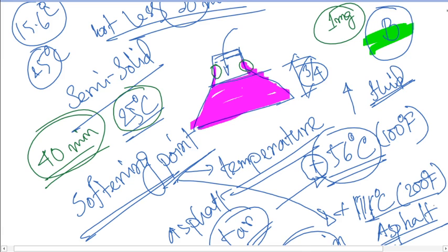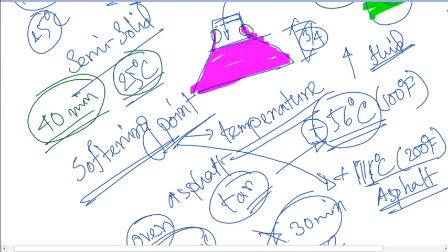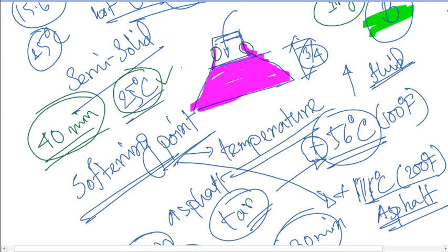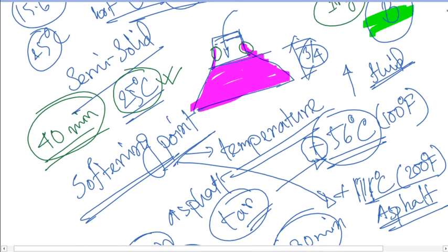Just because we need not ensure that this particular asphalt must be at 25 degrees centigrade when poured. We need not maintain 25 degrees or 15.5 degrees centigrade instantly whenever we have poured it up to 3/4 of the volume. Just because of what? Just because specific gravity is dependent on what? Volume.